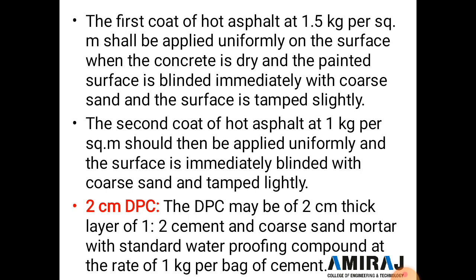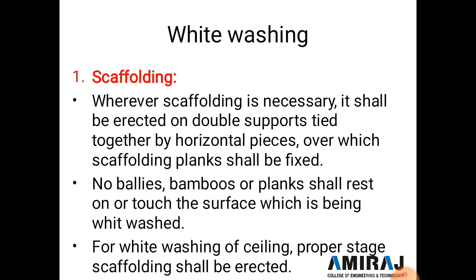Now next is a 2 centimeter DPC. So the DPC may be a 2 centimeter thick layer of 1:2 cement and coarse sand mortar with waterproofing compound at a rate of 1 kg per bag of cement.